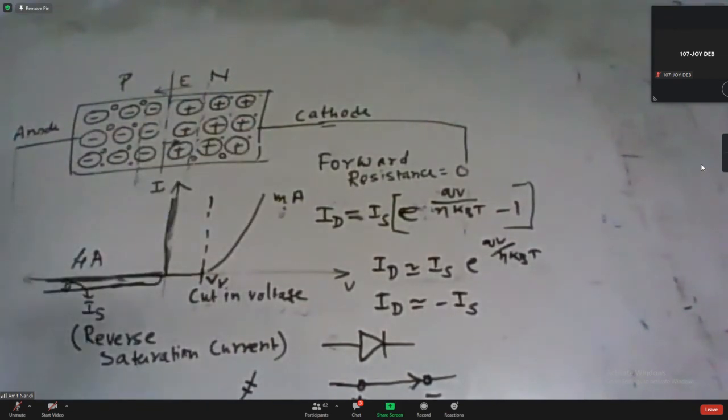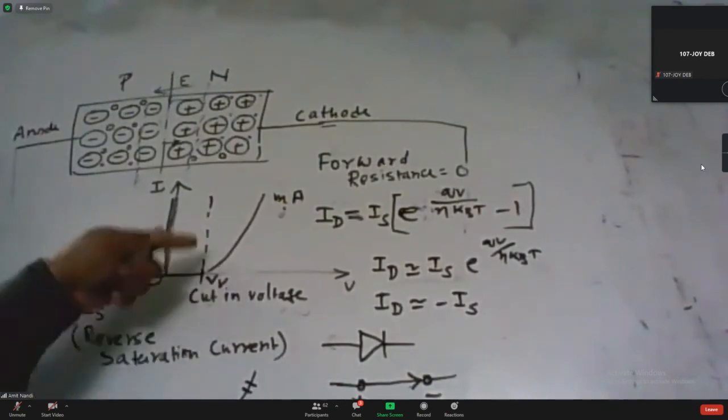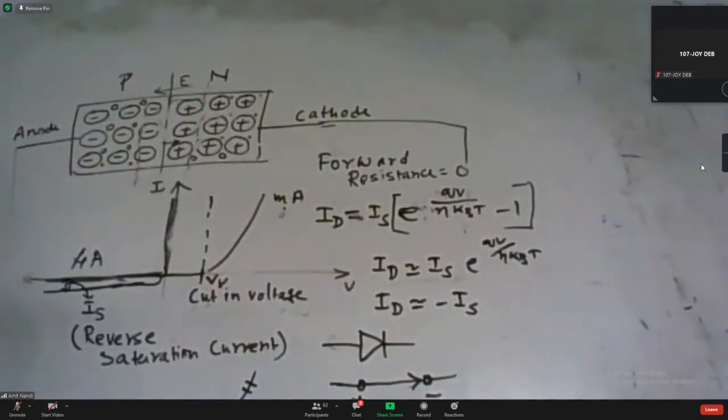We are taking a small region and we can consider that region is linear, and by taking the difference in voltage and the difference in current, we can easily calculate the incremental resistance of this region. Basically, a diode is a nonlinear element and a resistor is a linear element.